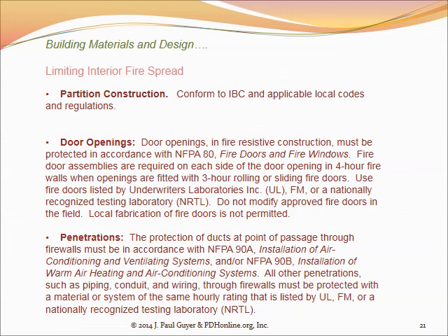Another important consideration is the air conditioning system in the building, because it has been learned that the air conditioning system is a good pathway for fire to move from where it breaks out in the building to other areas in the building. And it's not so much the flames that are the real threat as far as the air conditioning system is concerned, but it's the smoke. And when a fire breaks out in one area, you don't want the smoke to get to other occupied areas, because that's a big life safety hazard.